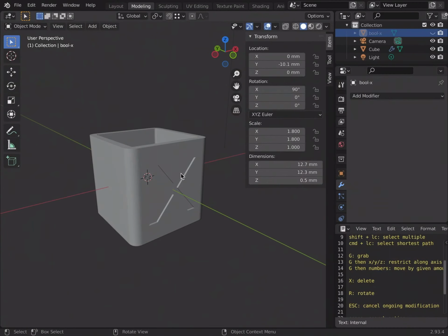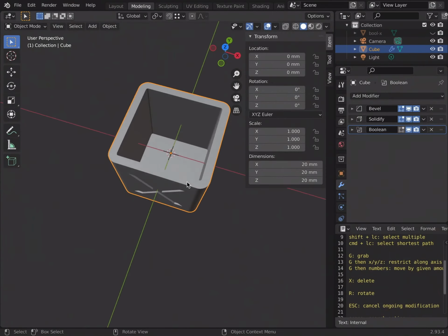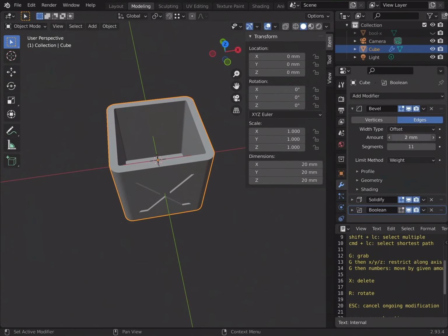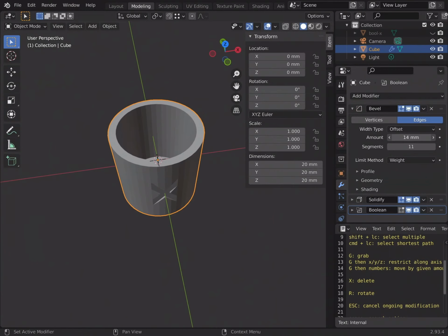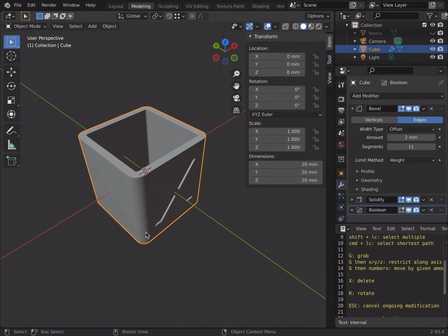And I've done all this by not moving mesh pixels around, but by using modifiers to, well, let's say mathematically enhance this. And this is great because if you want to change the amount or the size of the rounding, if you want to print an XYZ calibration cylinder, you can change these properties without fiddling with the mesh too much.